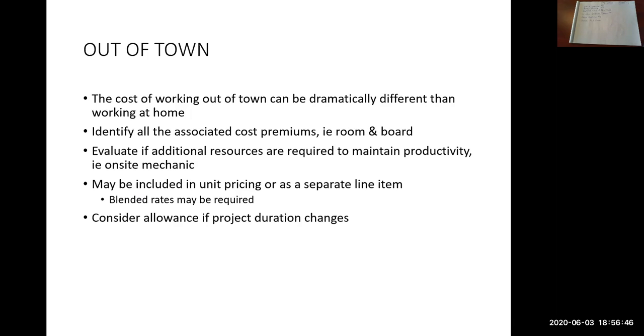So if you're thinking that the project is 10 weeks long, it might be worthwhile to consider adding in an extra number of weeks just for an allowance. Now, I wouldn't go overboard and do 4 weeks extra or 6 weeks extra. Maybe you do 1 week extra. It really depends on the size of the estimate, the dollar amount, the size of your crew, different things like that.